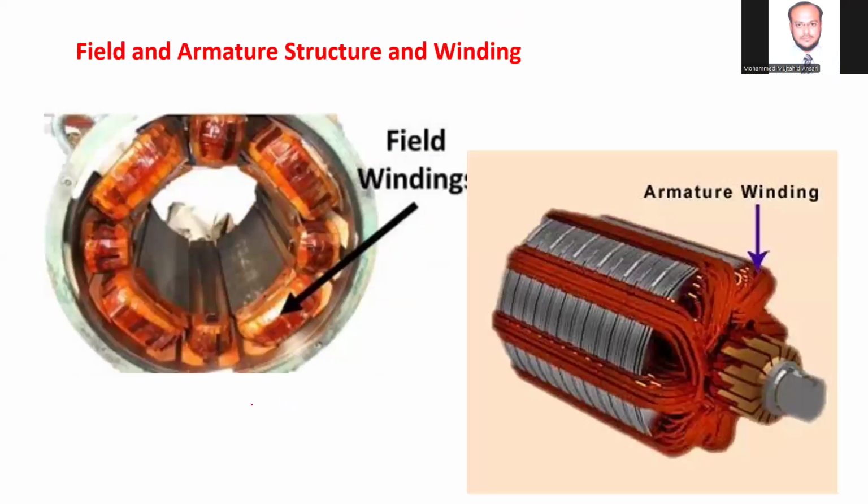So what is an electromagnet? There is a magnetic material, silicon iron, over which we do some winding. This winding is energized with a DC source, with a resistance over it, and it is controllable. So if you control the current in the coil, definitely the flux produced by the electromagnet is controlled.